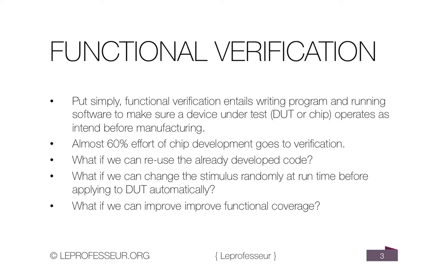So, put simply, what is functional verification? Functional verification means that you write some programs and you run simulation software to make sure that your device under test, or your DUT, operates as intended before manufacturing. For example, if you ship out your chip design data to manufacturing and it has a lot of bugs, you spend a lot of money, billions of dollars, and at the end you get this buggy chip which has a lot of functional errors, functional bugs, I would say.